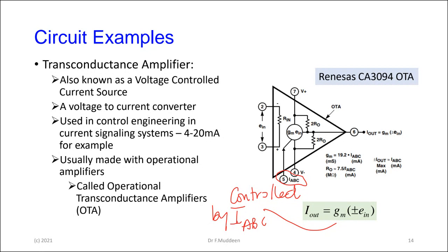So you have sensors at some part of the plant, and the sensors invariably would create a voltage in proportion to some sort of behavior, right? So you have thermocouples, or you have flow sensors and the like, and they generate a voltage in proportion to whatever is happening at their end. But to send a voltage a long distance is a little bit of an issue because of line resistance.